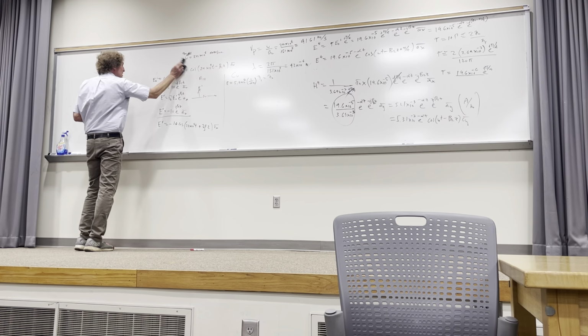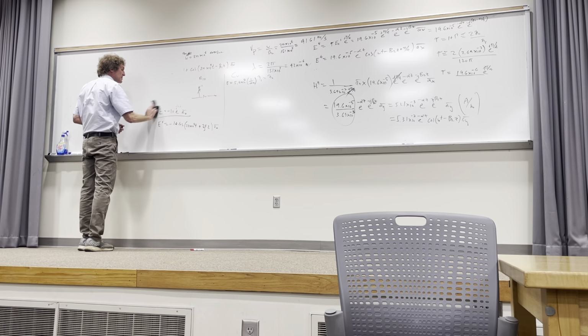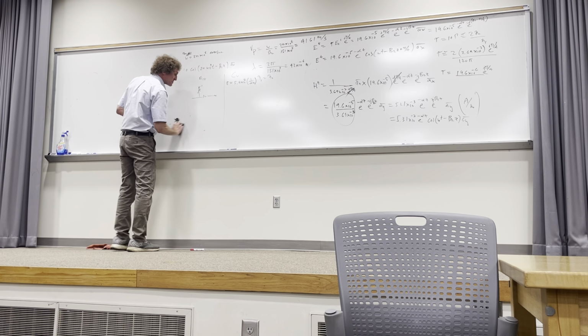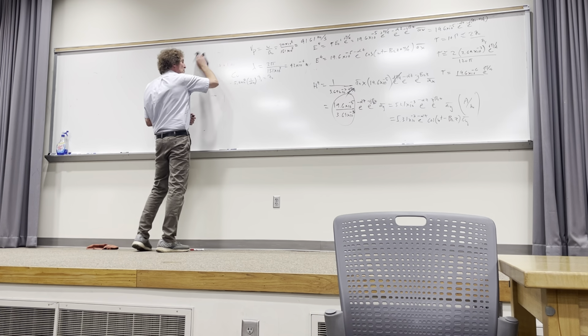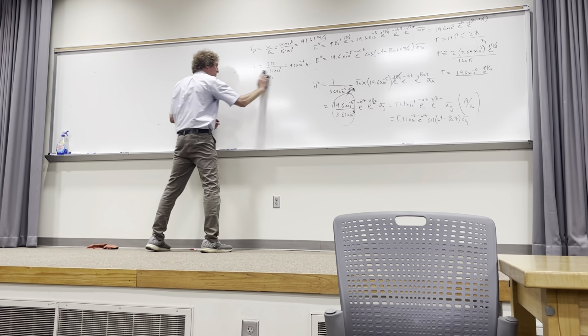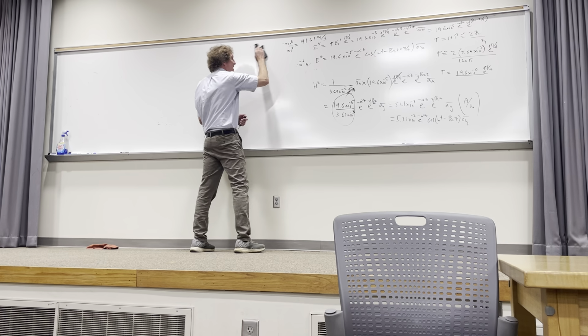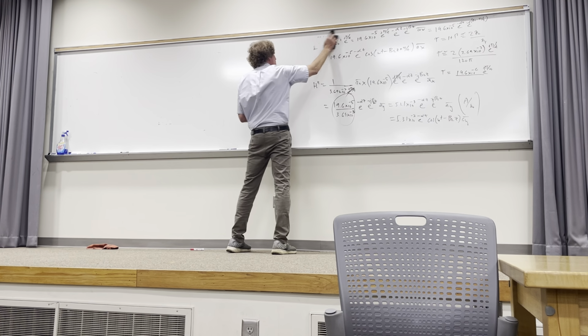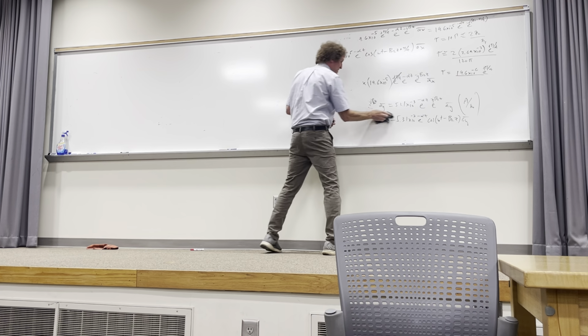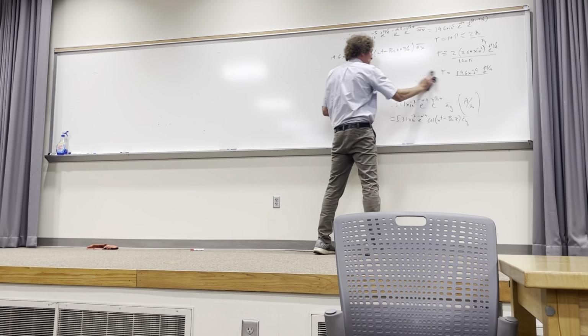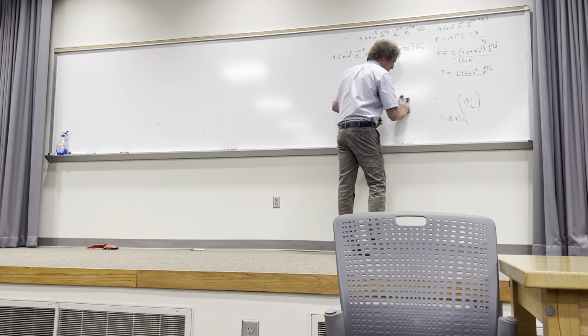Well, capacitance problems usually take the shape of either two parallel plates with some stuff in between them, two concentric cylinders with some stuff in them, or two spheres with some stuff filling them. And you always have to make an assumption that either the voltage or the charge is known, and then work to get the unknown, and then say capacitance is really equal to Q over V.